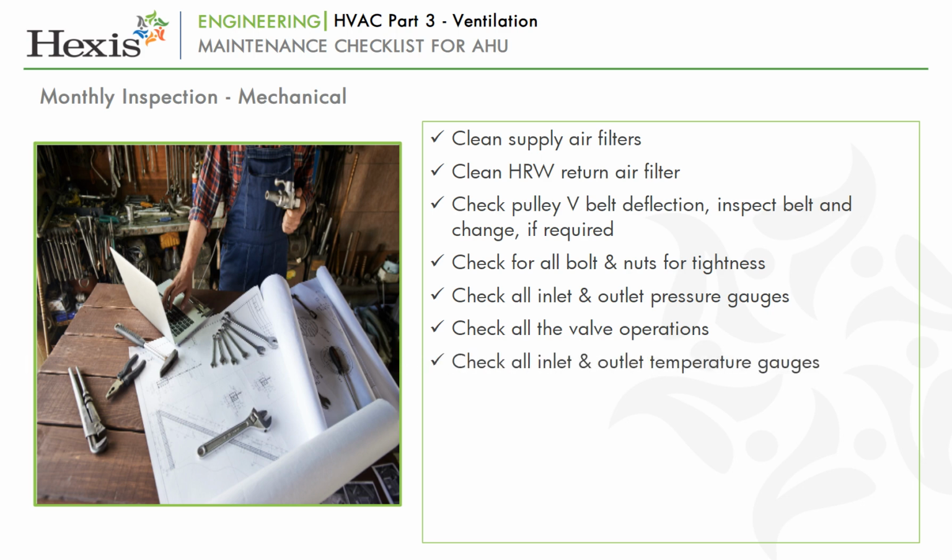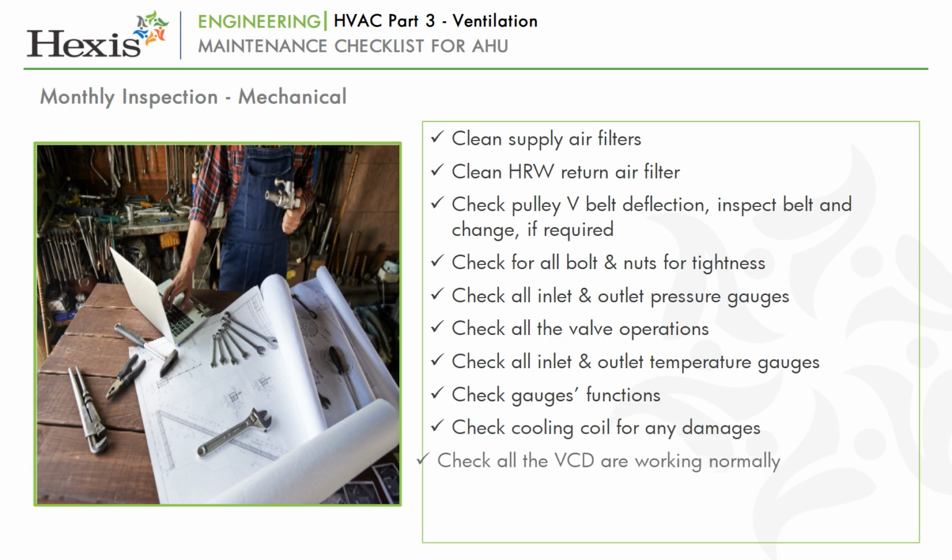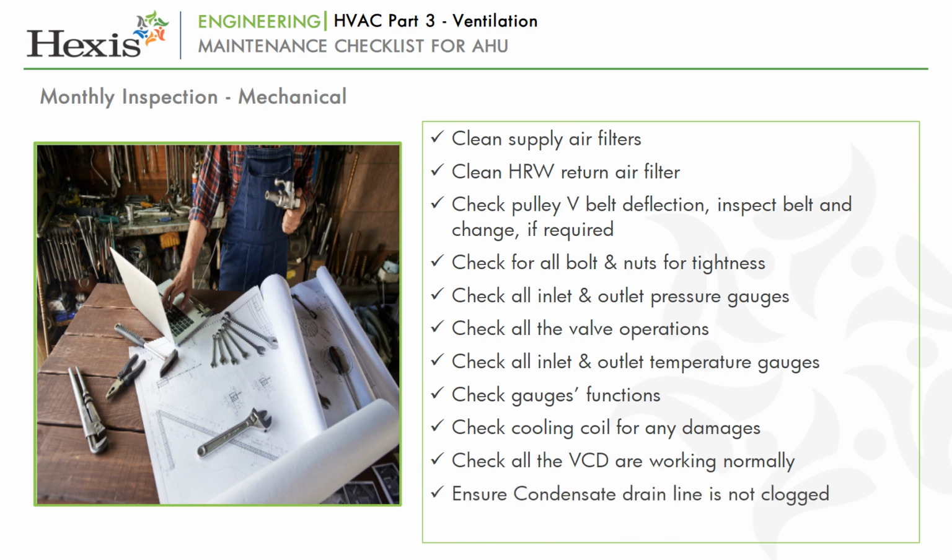Check all inlet and outlet temperature gauges. Check gauges functions. Check cooling coil for any damages. Check all the VCD are working normally. Ensure condensate drain line is not clogged. Ensure cleanliness of area after completion of job.